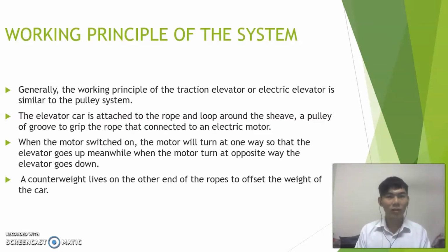So now for the working principle of the system. Generally, the working principle of a traction elevator or electric elevator is similar to a pulley system. The elevator car is attached to a rope, which is gripped by a grooved pulley that is connected to an electric motor.